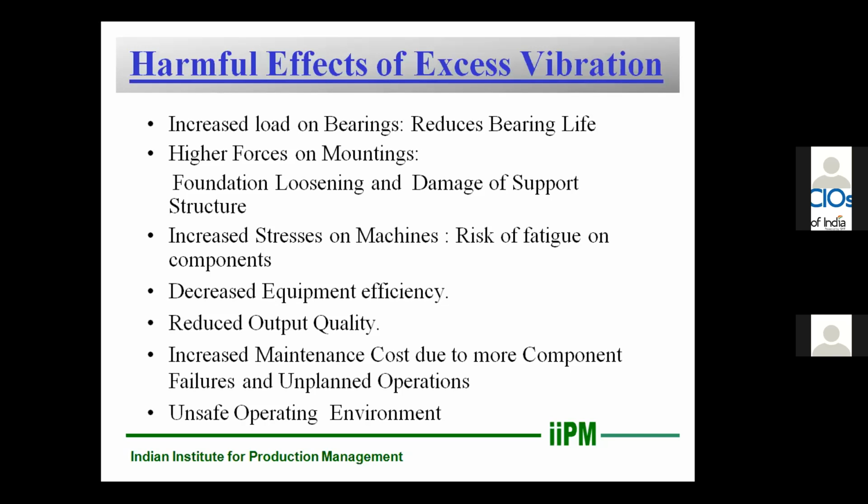This can become loose due to low frequency vibration constantly being generated by machine RPM. So what would happen when they become loose? Damping would increase as things rub against one another. So the next question is, what would happen when things rub against each other? A spectrum of frequency is imposed on the system, called noise frequency. It excites the natural frequency of the system.